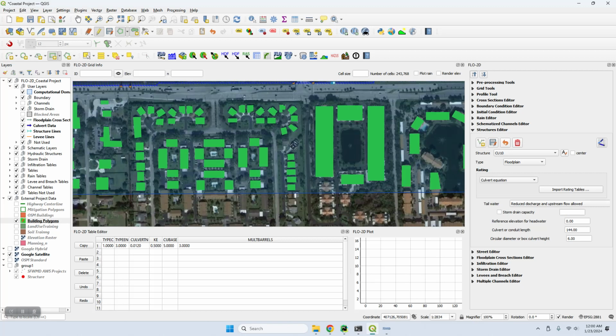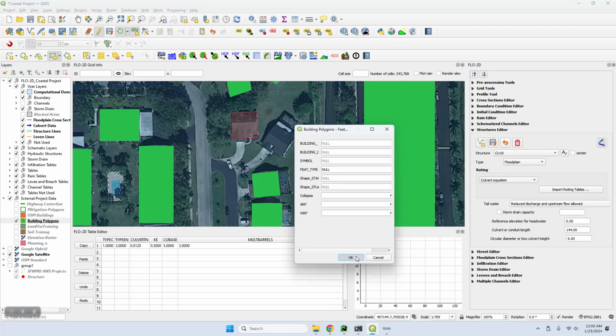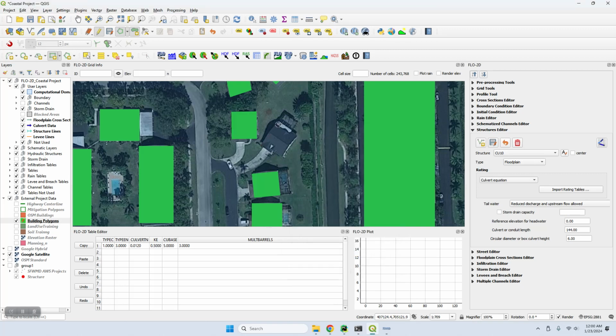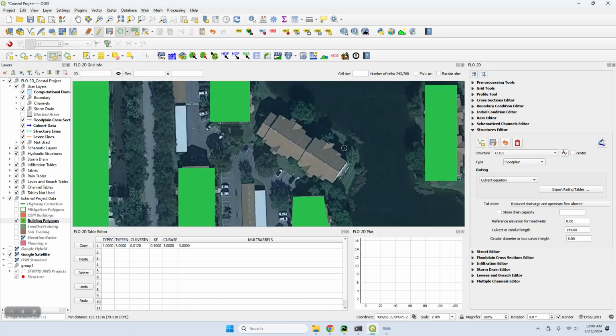And then a couple here that are irregularly oriented. For those, you'll grab the rectangle from 3 points, and I'm going to zoom in a little bit. This one will be a little different. It'll be left click, and then right click. That way you can pick up that angle. Left click, and then a right click, and again an enter. And I have another one of these that I've left over here. So just a left click, and a right click.